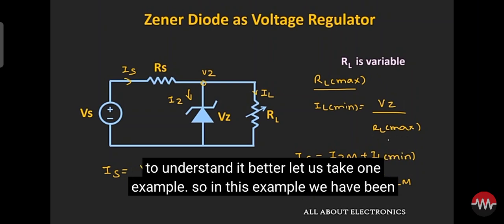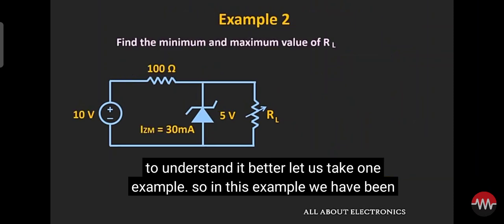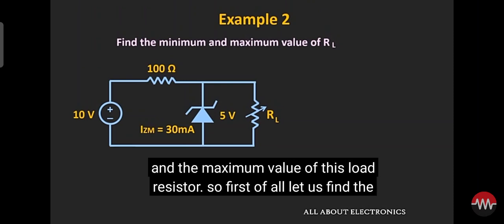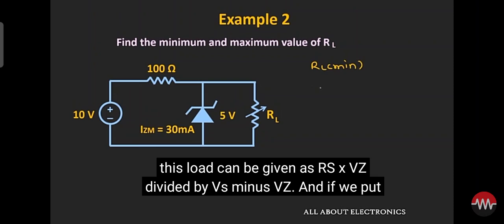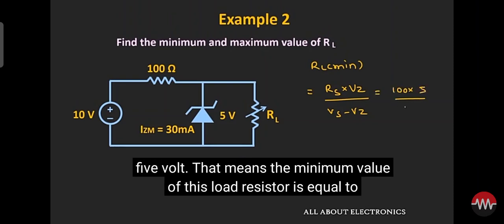So to understand it better, let us take one example. In this example, we have been given this Zener regulator circuit and we have been asked to find the minimum and the maximum value of this load resistor. So first of all, let us find the minimum value of this load resistor. And we know that the minimum value of this load can be given as RS times VZ divided by VS minus VZ. And if we put the values, then we can write it as 100 ohm times 5 volt divided by 5 volt.